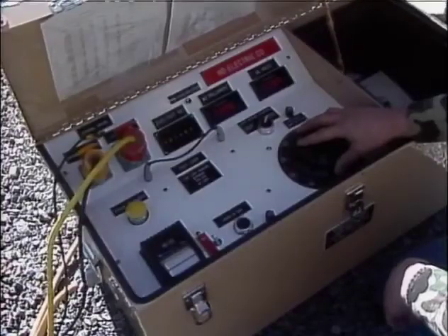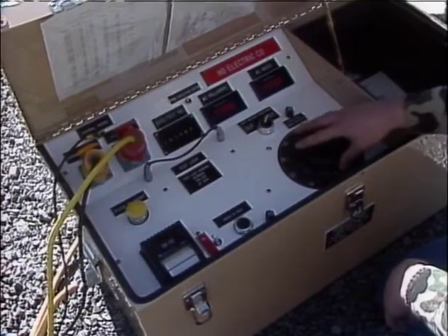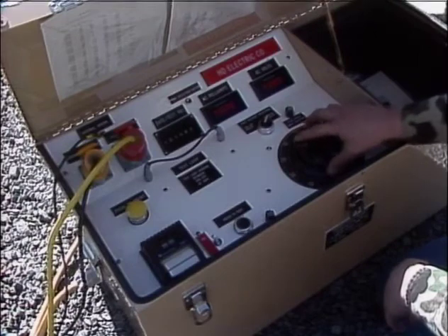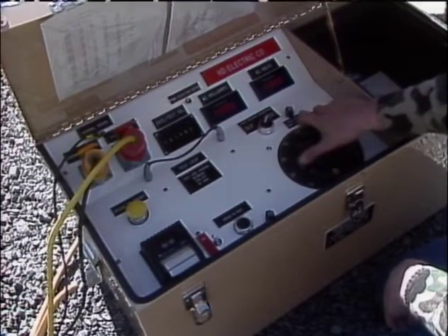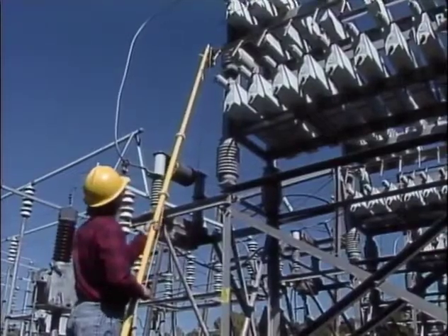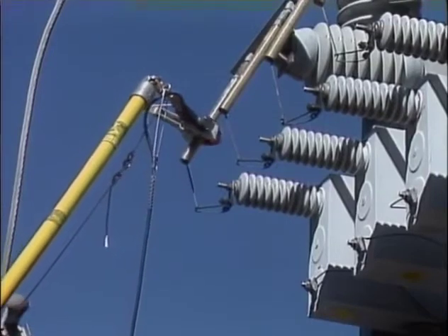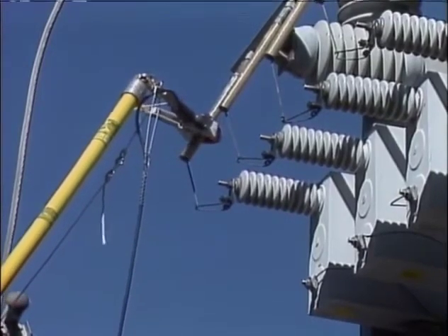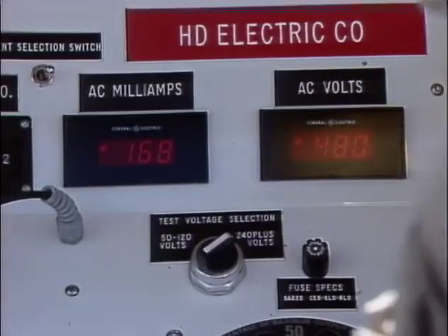After the test leads are connected, the voltage source is adjusted until the capacitor bank section is energized at the voltage specified by the manufacturer of the test equipment. Then, using a shotgun stick, a clamp probe is placed around the fuse of a capacitor to measure the current drawn by that capacitor. The current reading is allowed to stabilize. Then it is recorded.